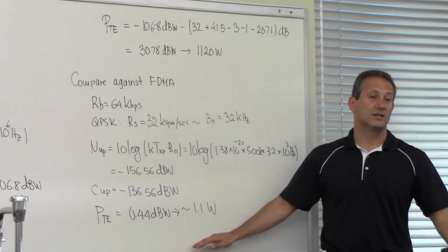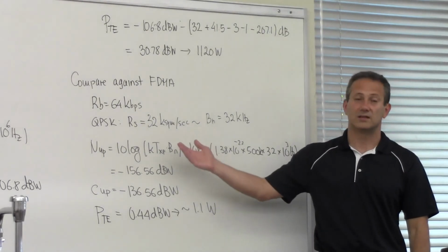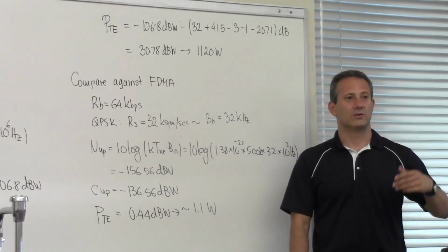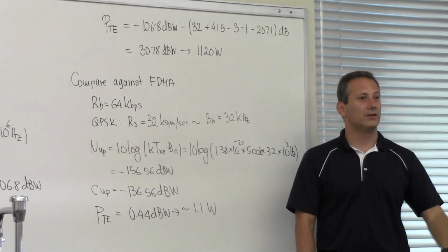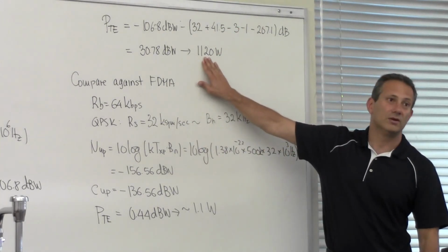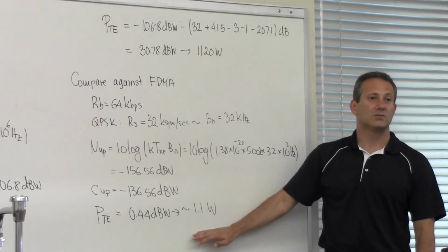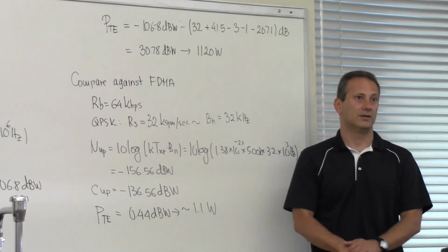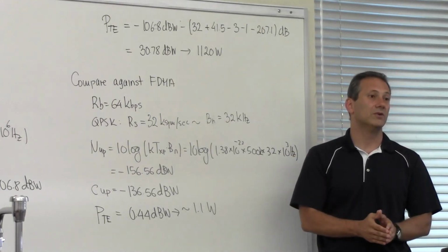And a lot of times, that's your chief constraint, how much power you can deliver. If these VSAT terminals are something that you have a soldier carry on their back, or something on top of a vehicle, or on top of an airplane, or sitting on the side of a house, then you cannot really furnish this much power, right? It has to be something much lower. And that's why a lot of satellite systems still operate FDMA, because it allows them to scale their power relative to the portion of the bandwidth that they're using.